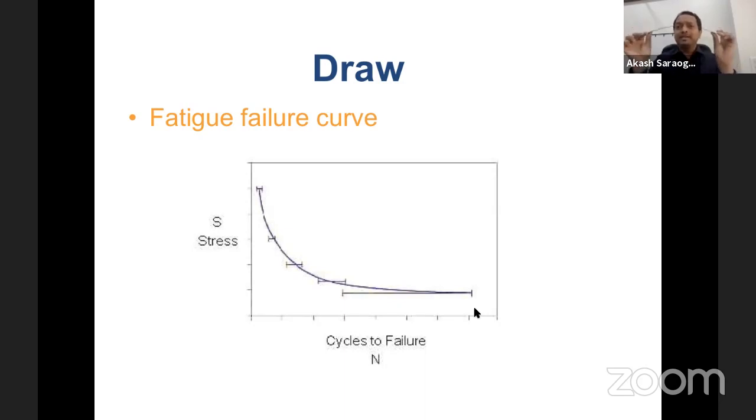If I bend the scale with a very significant stress, it is going to break in a single cycle. If I bend it 200 times like this, maybe when we reach 200, it is going to fail. But for any material, the amount of stress that it will take if I do this 10 million times and then it fails, that is the endurance limit of that particular material.